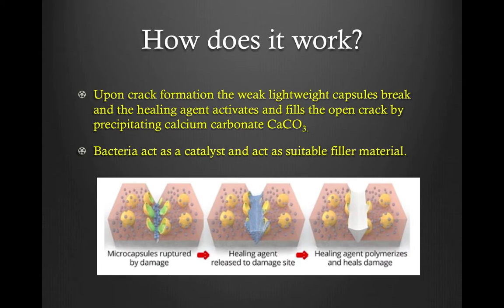Moving on to how this method works. Upon crack formation, the weak, lightweight capsules break and healing agent activates and fills the open crack by precipitating calcium carbonate. The bacteria in this case act as a catalyst and transform a precursor compound to suitable filler material. As you can see from the diagram, upon a crack forming, microcapsules are ruptured and the healing agent is released. I will give a few moments so you guys can take a look at this diagram.